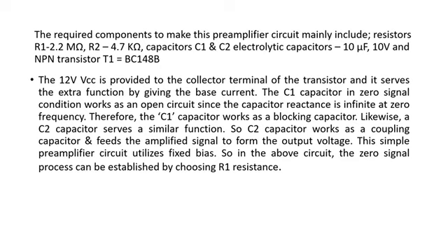Here the capacitor C1, in zero signal condition, works as an open circuit, since the capacitor reactance is infinite at zero frequency. Therefore, capacitor C1 works as a blocking capacitor. What they say is that at zero frequency, if the reactance of the capacitance is infinite, then the particular capacitor will act as a blocking capacitor.